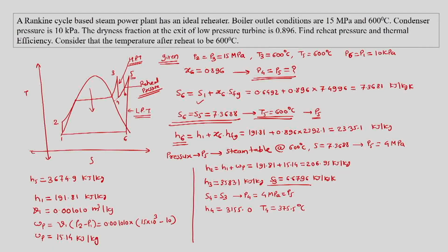Using these conditions, by one match, S6 equal to S5, we can identify the pressure, and by making the other match, S3 equal to S4, we get its temperature known, or along with temperature we can also know whether the point is inside the dome or outside the dome. We will go ahead with the next example.